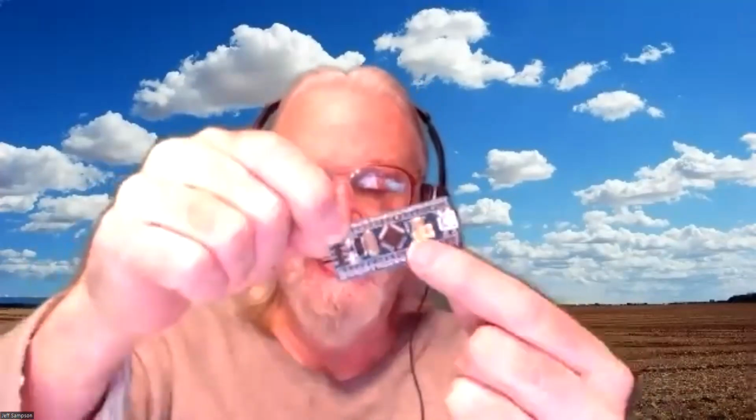Whereas on the Blue Pill, the way they've got that one set up, it's got jumpers on here. You can set it to, I think, the serial loader. If you move that jumper and hit the reset button, it goes into a serial loader. So there's a couple pins out here. You can hook up an FTDI adapter to it and load it through serial. And once you get the HID bootloader put on, you don't have to do any of that extra stuff anymore. The thing's running, you go to Arduino and say upload, and it does. And supposedly it'll go back to running, but you may have to unplug the cable and plug it back in to get the interface to come back up right. So in general, you can make that work on the Blue Pill.